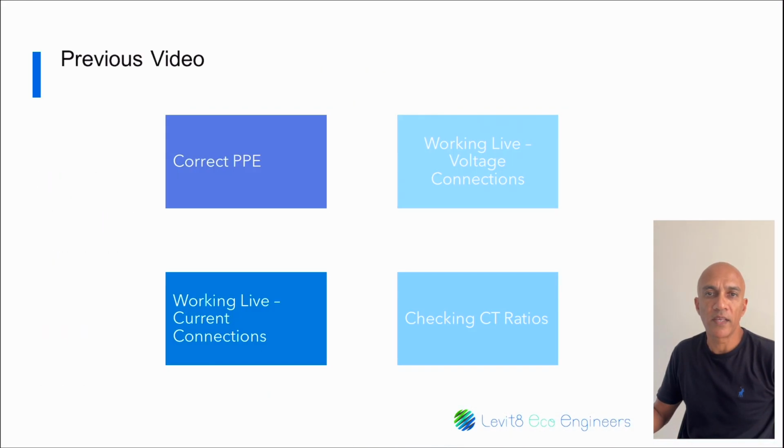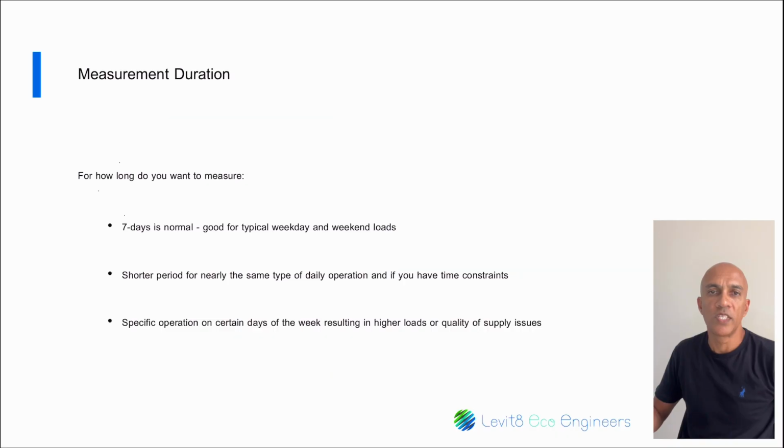Now you are at the stage of applying the settings so that you can leave the instrument to record for a specific period. You would determine the period based on your requirements, but in most cases, a 7-day recording is desired because it will give you a good indication of how power is utilized by the facility for each day of the week. There may be a day or days in the week when load is higher, likely in a factory type environment. Mondays may have high loads in the morning due to machines starting up, and some places may be closed in the weekend and will only have minimal loads during those times. You will make the judgment on the duration based on your homework of the site and recommend the best option to your customer.